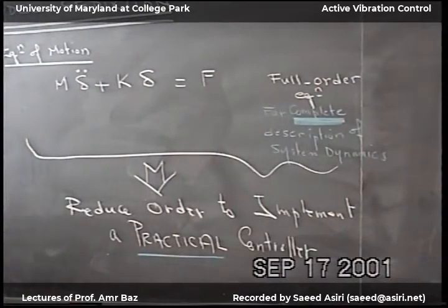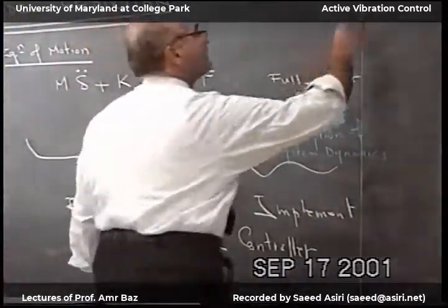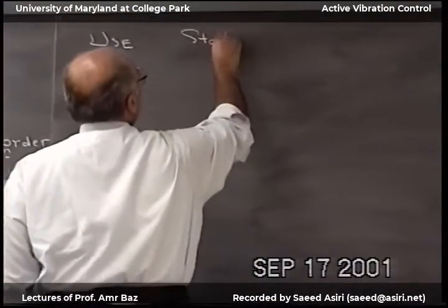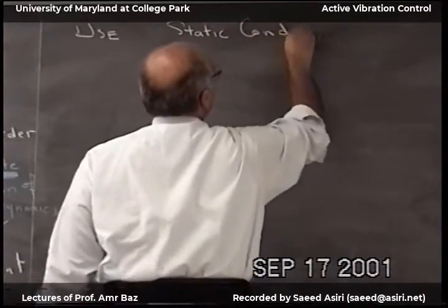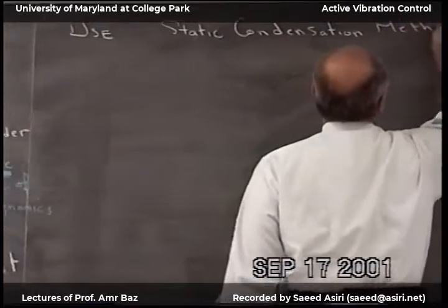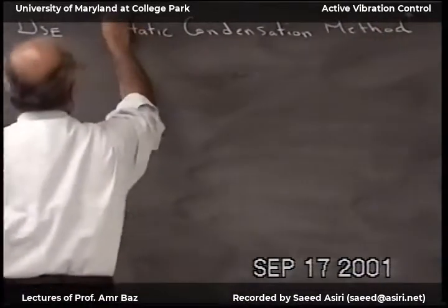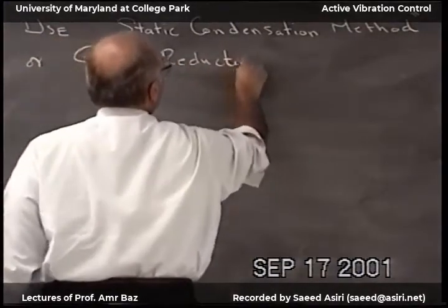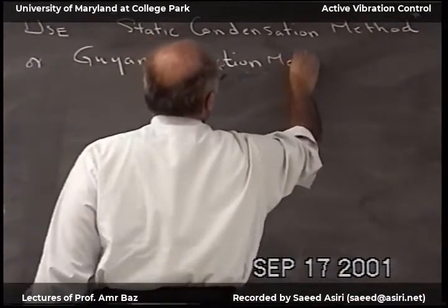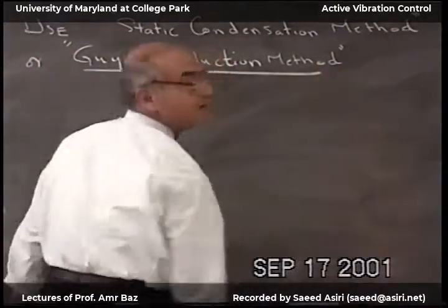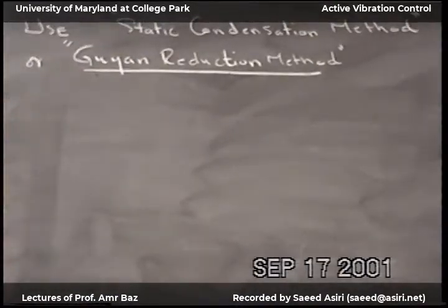Okay, so the way we will do it, we use the static condensation method, or the Guyan reduction method. And all finite element packages have this model reduction in it.